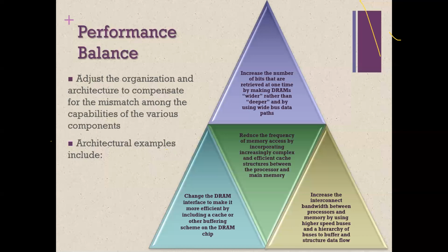from Accra towards Nsawam. So in that case, then you can move the cones also back to the other lane facing Accra. And by so doing, you could create 4 or 5 lanes, because the traffic that is flowing to the other end is minimal. And so even if it was only 1 lane, the traffic will flow without any congestion. And typically, that is what we do.